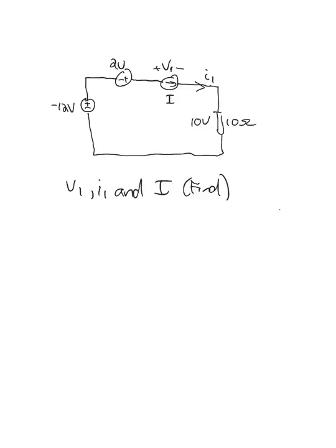So in this circuit, if you just apply Kirchhoff's voltage law going around the loop, starting at this point and going around clockwise, then you get minus 12 volts. Because it's minus 12 volts and we write down the sign that we get to first, minus 2 volts plus V1 plus 10 volts, and that all has to be equal to 0.